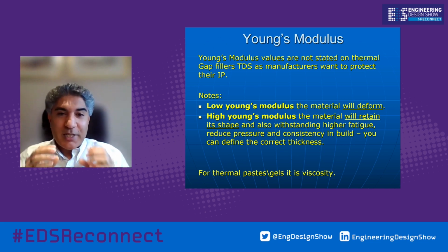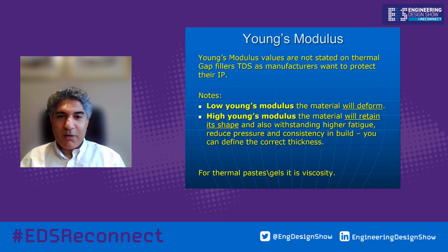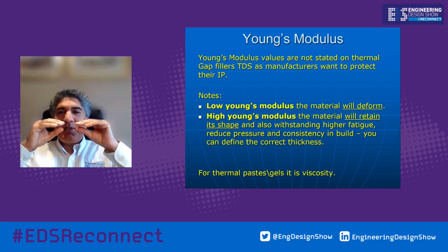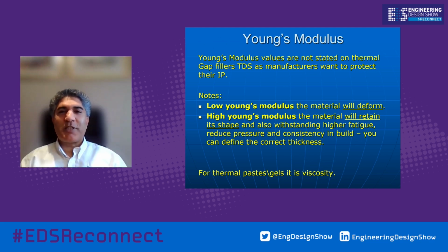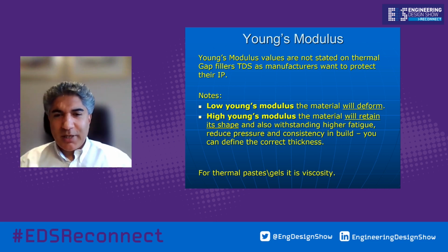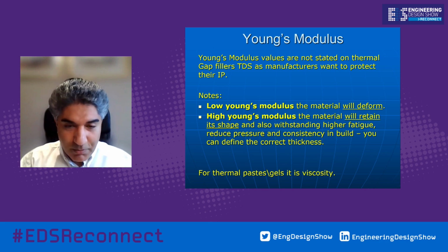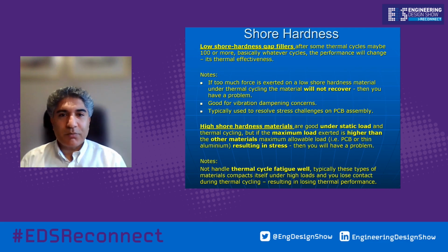risks. What we're trying to say is please have it not too low, so medium to high, so it retains the shape. It can handle the fatigue element of it, so you're not having that issue of why is my thermal resistance getting too high? It's because the material is oozing or pumping out and isn't attached to the substrates. In thermal paste, we call it the viscosity, an element of ability for it to pump out, or to minimize the pump out.